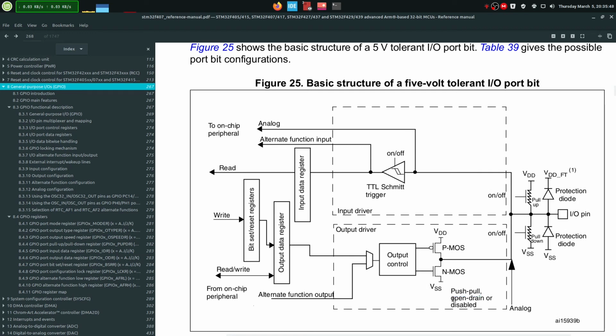It can also do open drain, as you can see over here. This means that this transistor is turned off, and this one, if it's on, is connecting this point to the ground. When it's off, it's just open. And when both are disabled, that means this pin is in a state of tri-state, as it's sometimes called, or high impedance, and this is because these transistors are open. But well, you might ask, there's going to be some kind of resistance.